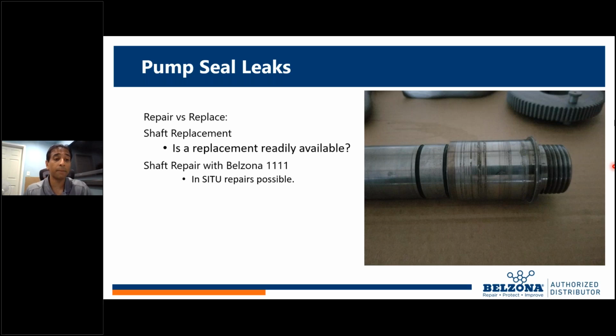Pumps are a big deal. You don't always think about how your pumps are going to fare, because you might have replaced a section of pipe in another part of the line, but it might have put enough strain on the line that now your pump is vibrating. It only has to be a little bit of a vibration. If you don't necessarily have good vibration analytics going on, such as a Marlin system, you might miss it.